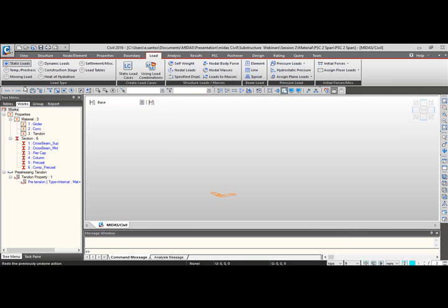We also have something called tree menu. In this case, we have the tables tab, in where you can obtain the different properties of the model using the tables. So let's say that you have different model nodes generated in the program. From here you can obtain a table which you can export to Excel and so on.